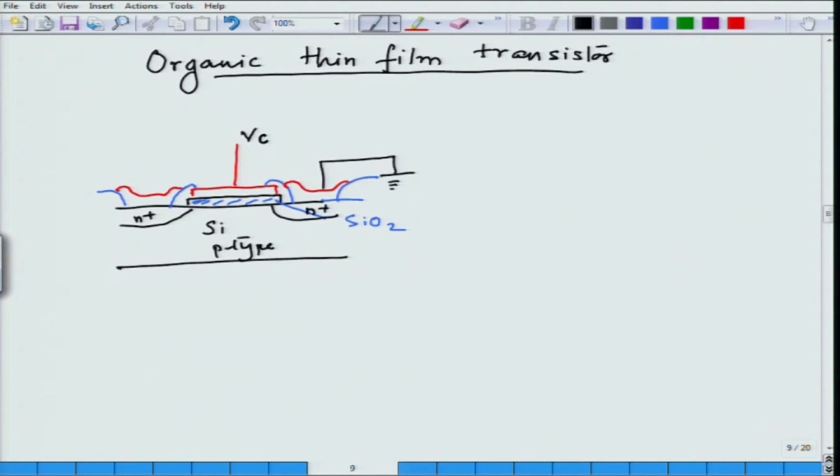This was my gate voltage, and this was my drain voltage applied. This was my MOSFET, where I started with the semiconductor, built on it and created a MOSFET structure, used the inversion of this structure to create a channel, and the voltage between the source and the drain is then used to flow the current, and I have the switching behavior of a transistor.